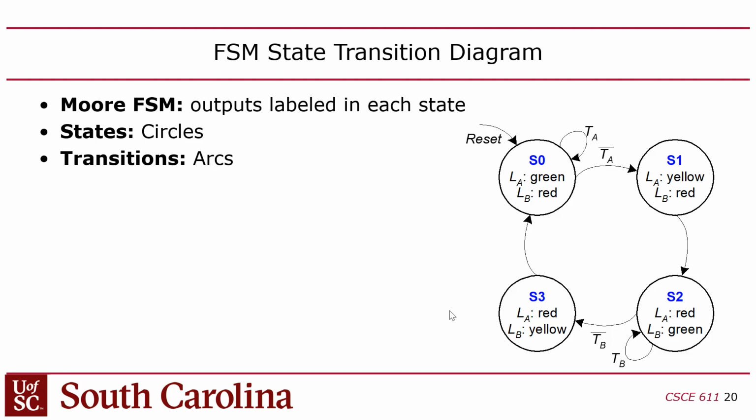And so if you have traffic on, like I said, as long as you continue to have traffic on academic, you're going to keep that green. And in this case, there's no timer that'll time out. It'll just stay green indefinitely until we have no traffic on academic, in which case it switches to having a yellow on academic and it keeps Bravado red, and it'll stay in that state for 1 clock cycle.